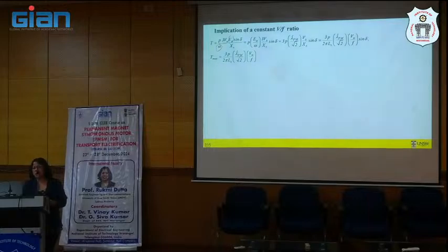The ratio of these two quantities is actually your flux linkage, because flux linkage times omega is your EA. So the ratio of EA over omega is the flux linkage. And in case of PMSM, it's a constant value: the flux linkage of the PM or magnet.